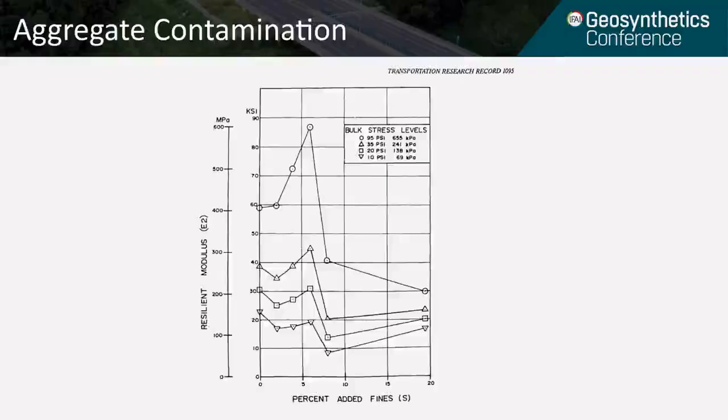Another item to consider is contamination of the aggregate layer. It is quite typical that the roads on a solar farm would remain unpaved. And although using a geotextile to act as a separator between the subgrade soils and the import aggregate would minimize this possible contamination, due to cost, it's often overlooked the whole process from start to finish.